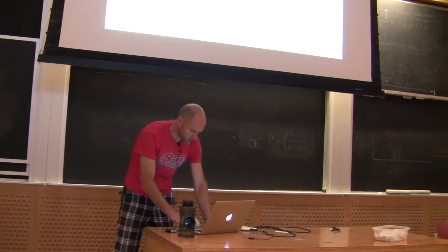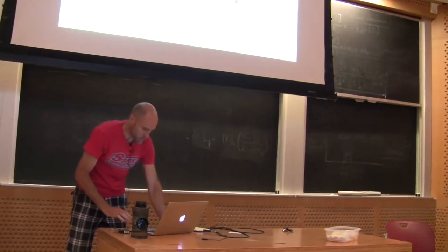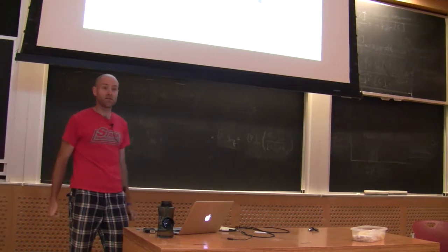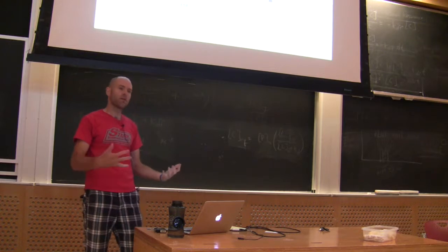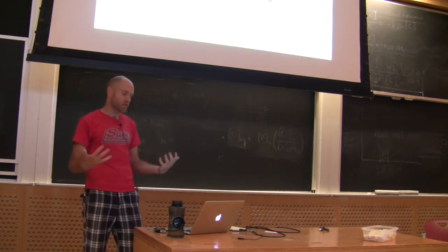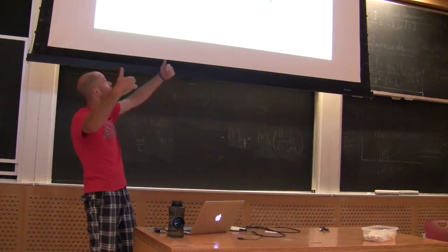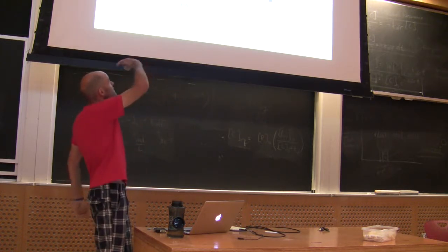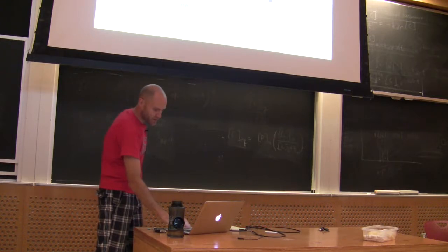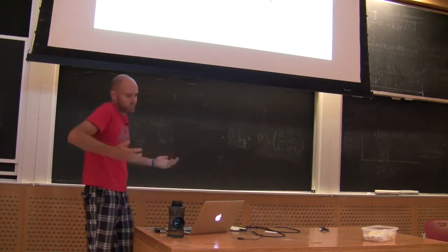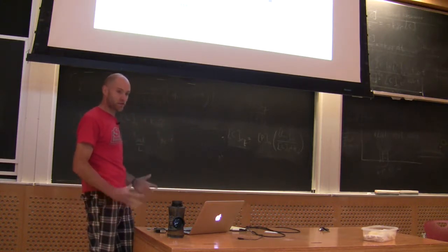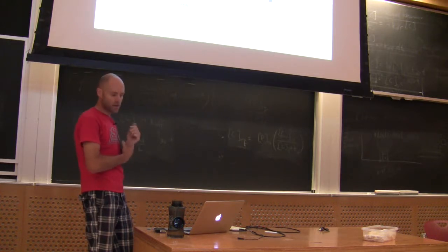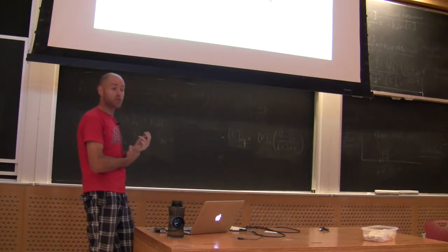So I change that to quadratic cost and run value iteration. Now there's already a signal far from the goal, and I get a smoother cost to go. My policy is a little different, right? This time they all come here and then go down. I could change the orientation of that quadratic cost and move that point. That's not central, but the cost you specify can give you fundamentally different results, with different properties. They'll run different ways on different robots, right?